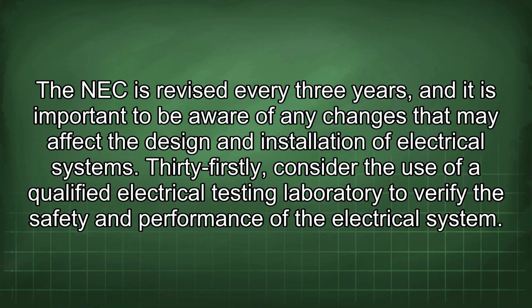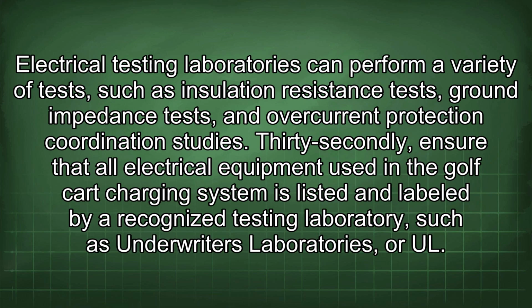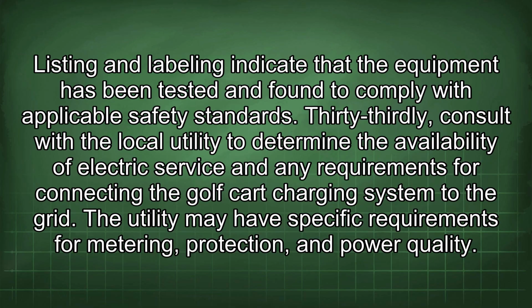31stly, consider the use of a qualified electrical testing laboratory to verify the safety and performance of the electrical system. Electrical testing laboratories can perform a variety of tests, such as insulation resistance tests, ground impedance tests, and overcurrent protection coordination studies. 32ndly, ensure that all electrical equipment used in the golf cart charging system is listed and labeled by a recognized testing laboratory such as Underwriters Laboratories or UL. Listing and labeling indicate that the equipment has been tested and found to comply with applicable safety standards.